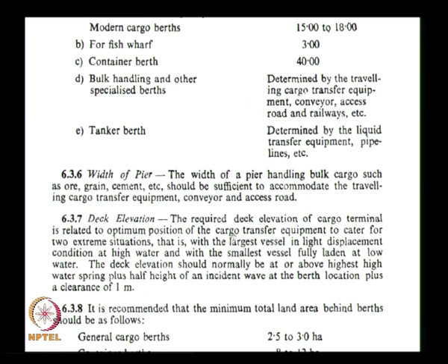Another important parameter is the deck elevation. Deck elevation depends on various factors, but the main thing is the largest vessel in light displacement condition at high water, that is in highest high water you have the largest vessel in light displacement, and the smallest vessel fully laden at low water. The deck elevation should normally be at or above highest high water springs plus half height of an incident wave at the berth location plus a clearance of 1 meter.